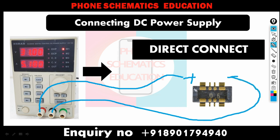Also, you can find a TP, a test point, on the positive line on the motherboard, like some of the points near the battery connector or the charging connector. So you can find which point is VBAT. Connect the multimeter, oh sorry, to the positive line. For this, put the multimeter in beep mode, one probe on positive, and check one by one.